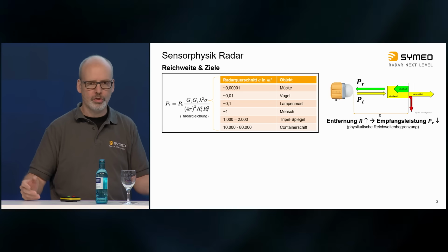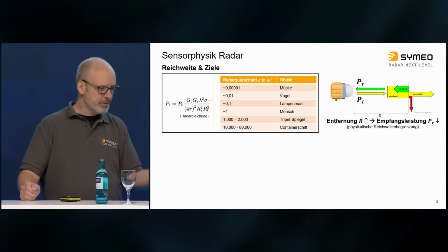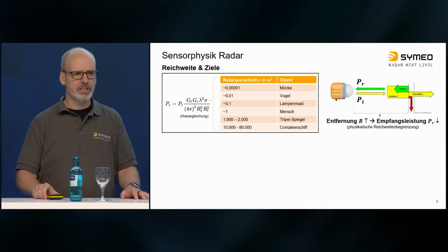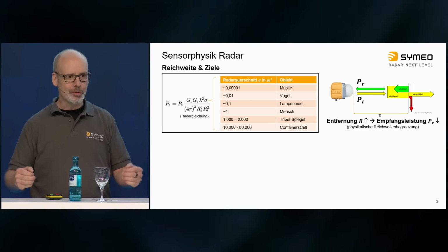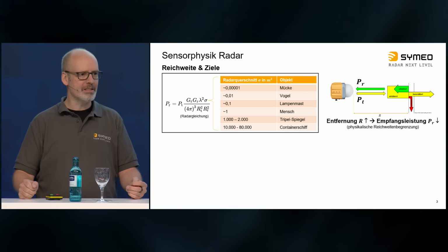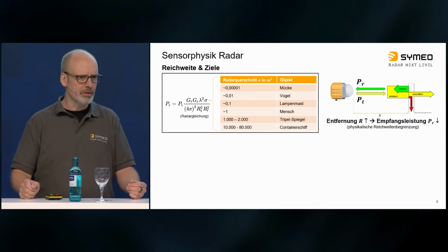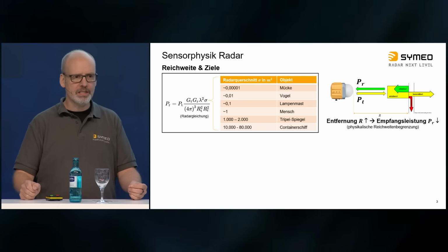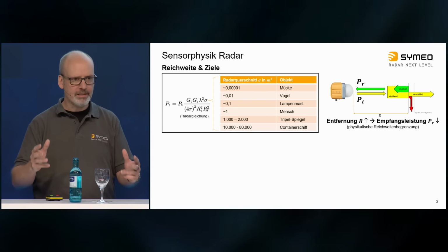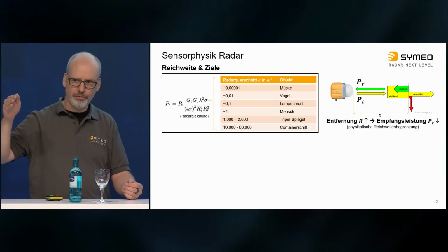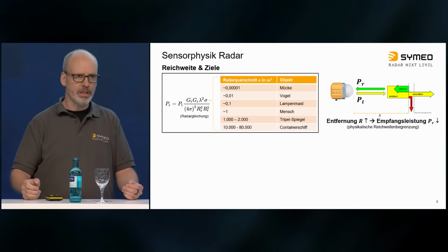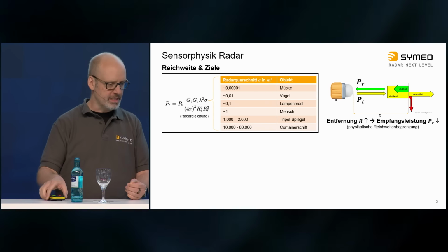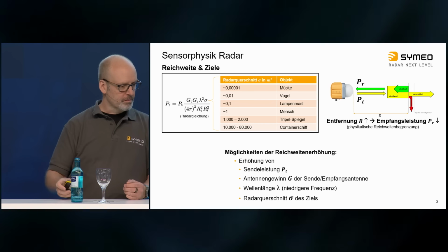This is why radar is used a lot in marine activities. There are objects like vessels, and they reflect very well. And there are things in between, for instance, the human being. The human being has a radar cross-section that you can see here. That's a medium good target, if you will. The radar reflection depends on the frequency. If I want to see a poor reflector, I can go up in frequency, to gigahertz or lower terahertz, and I can also see bad reflectors. So radar is very flexible.